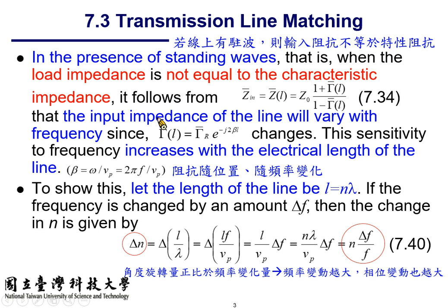So it contains the description of frequency, which means the reflection coefficients viewed at different frequencies are different numbers. So the input impedance Z in is also a function of frequency. It becomes a number sensitive to the change of frequency. In other words, the transmission line response is sensitive to the change of frequency. As a result, the signal passing through the transmission line will become so-called dispersive.